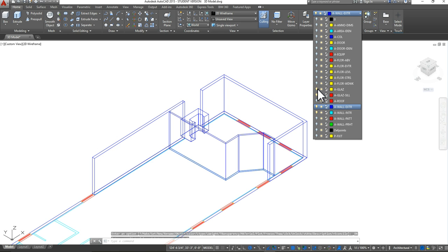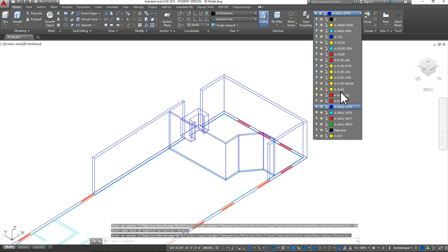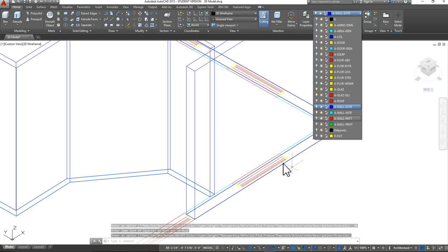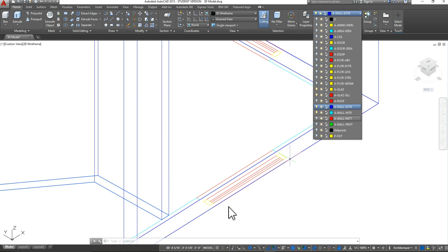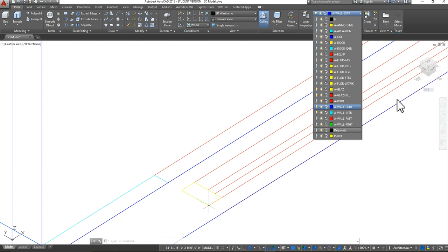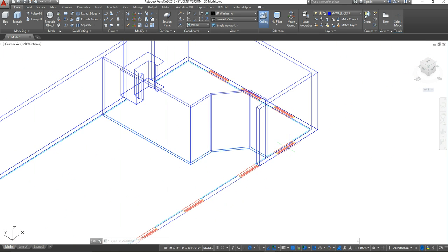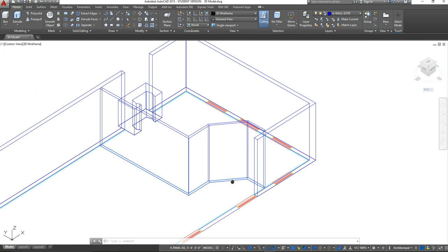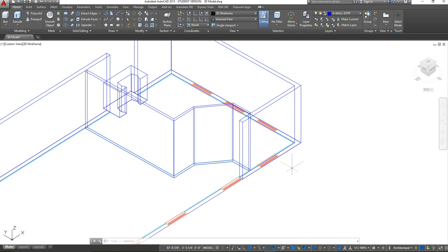Okay, and if you wanted to, you can also do the glaze, and that'll create a more defined look again on where that window placement should go. So it's up to you, whatever makes it easier for you to see it in your model. So in my case, I only want to create those window openings for the area that I am creating my model of. So I'm only going to do it for this window here, that one, and that window.